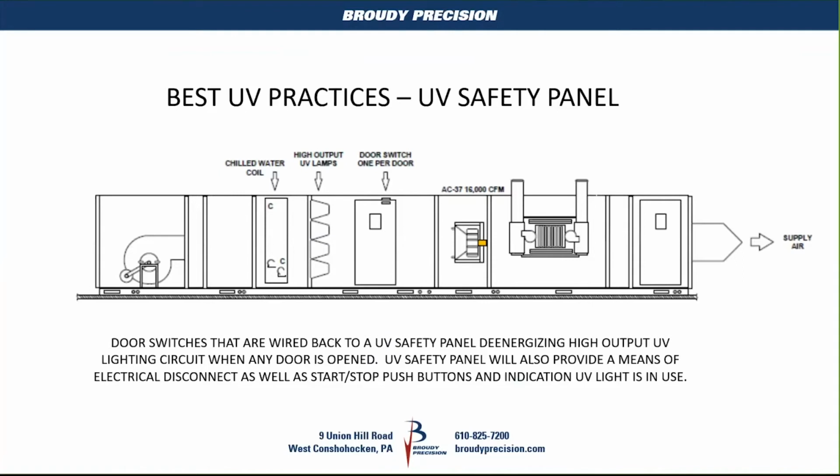What we are seeing with the outbreak of the current environment is a surge of these panels being sold. So our contractors are installing these ultraviolet germicidal irradiation systems, and they're buying our safety panel to control them. It's essentially a straight, completely electrical panel that is intended to immediately turn the UV lighting circuit off if any of the doors around the UV light rack are open.